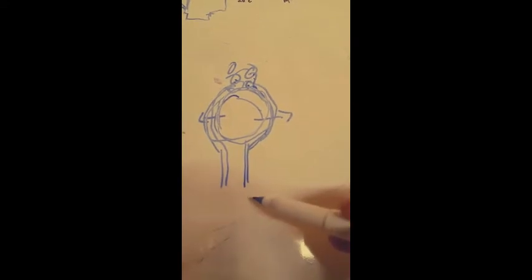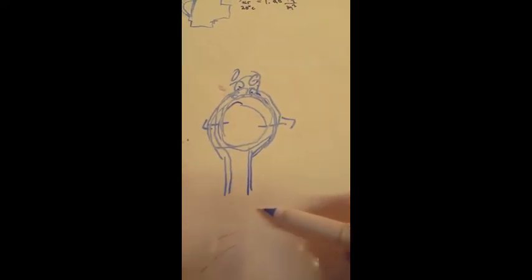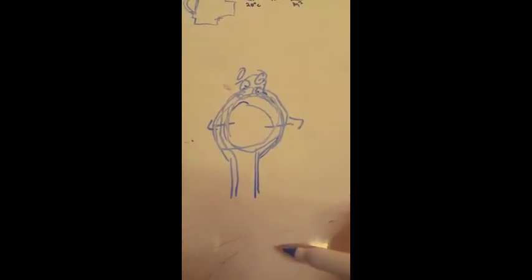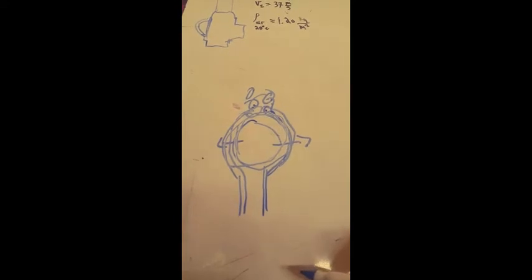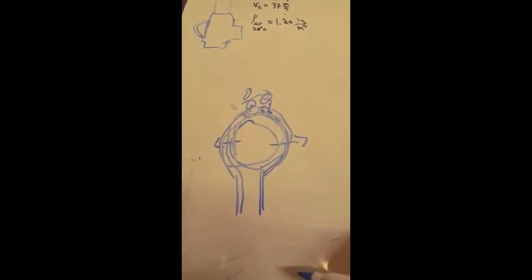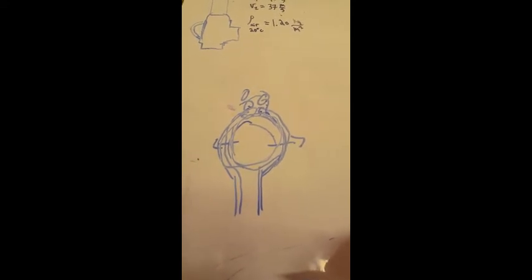The actual reason for this is called the Coanda effect, which is the tendency of a moving fluid to stick to a curved surface, like air over a plane's wing. When a jet of air moves through a surrounding stationary atmosphere, it pulls some of the stationary air along with it. This produces a low pressure shell around the jet stream.